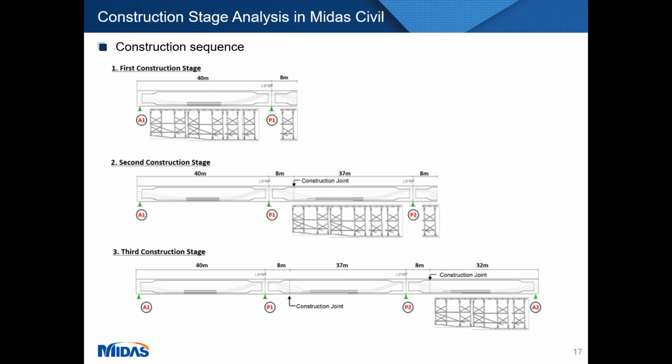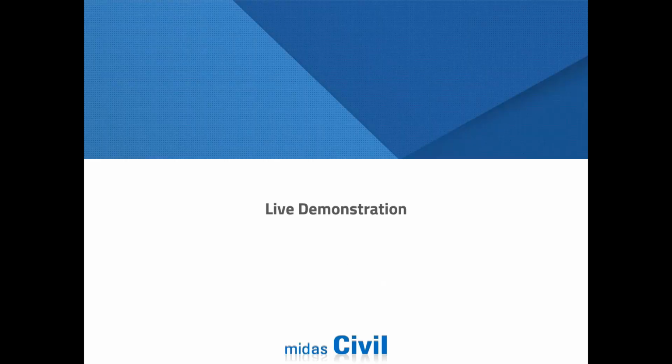Now let's move on to our software demonstration part, where we will see how to simulate such a construction sequence, plus how to take into account the time dependent effects of creep, shrinkage, compressive strength, and pre-stressing for our analysis. Now let's move on to the live demonstration. Let me open the software for you, and let's see the demonstration of construction stage analysis in MIDAS Civil.